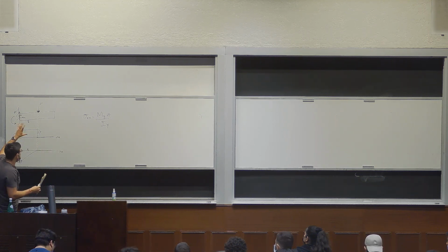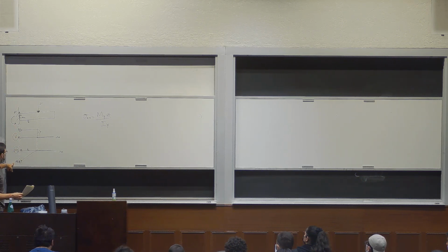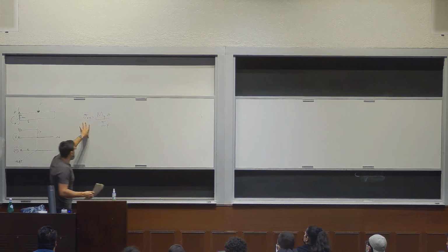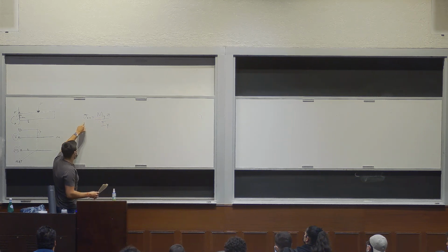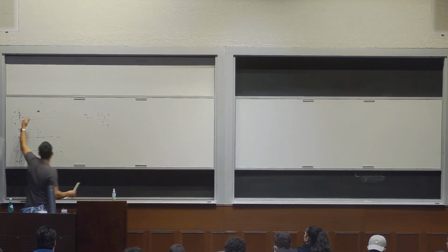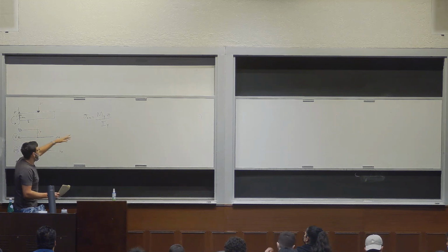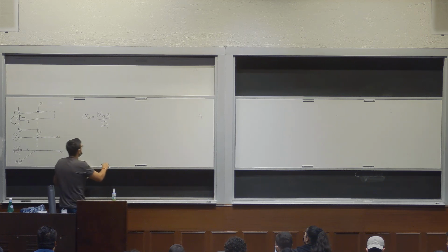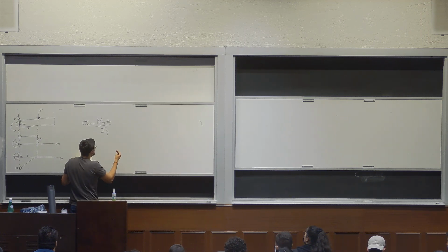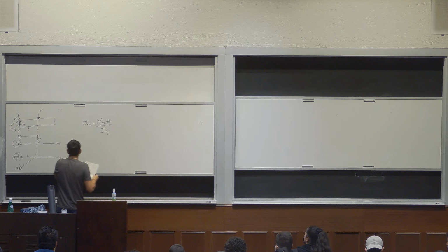So if you were looking at this specific example, you find your shear moment diagram, you find that at the base the moment is PL, right? You would go to this equation, plug in PL for My, and then find the location at which this is greatest, which is the highest z, which is either the top or bottom surface, and then divide by Iy, which would be provided by the geometry of the cross section. Okay, this is in the case of unidirectional bending, right, with a symmetric section.